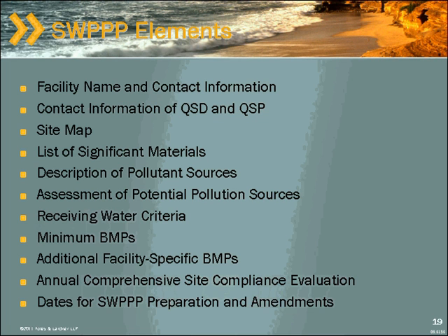Right. And that is the issue, Wayne. What I can talk about is how the state of Washington, who recently issued their industrial permit, handled it. They did prohibit new discharges to 303(d) listed water bodies unless the new discharger could demonstrate that they were not threatening to discharge one of those listed pollutants. I'm very much simplifying their language. So if they potentially could discharge nutrients to a nutrient-listed water body, they would not be allowed to go into the system, which has significant land use implications, as I think you know.